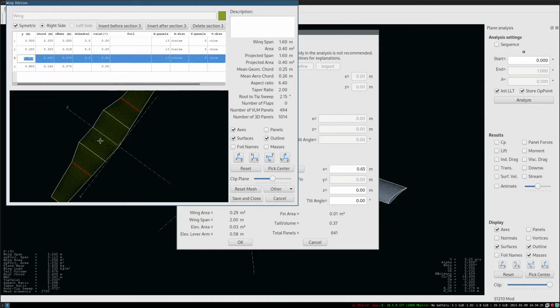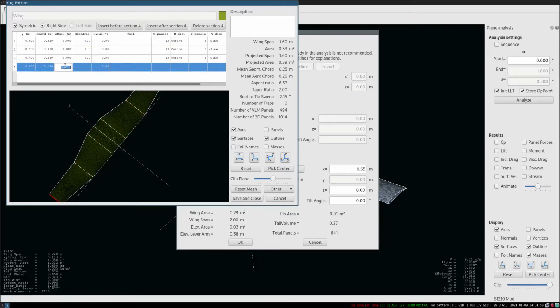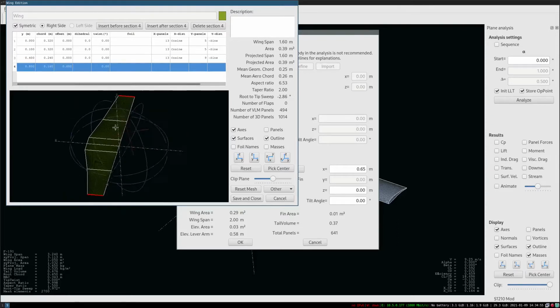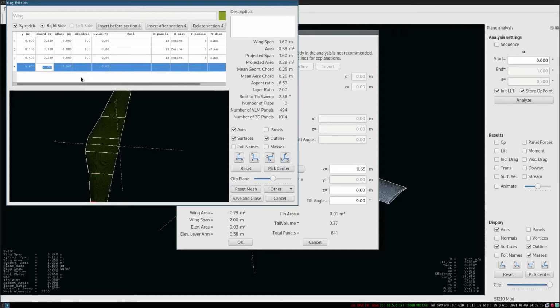Yep, we're going to bump that. Our middle section will be offset 0 at Y position. We get a 20 centimeter inboard section that is unchanged. We're going to assume we have a wing spar running down the leading edge, so we're going to have an untapered leading edge and a tapered trailing edge. That's quite a nasty progression. Something like that, I suppose. And we'll go to 0.16 here. Maybe a bit aggressive. Let's go to 0.24 on both sections.